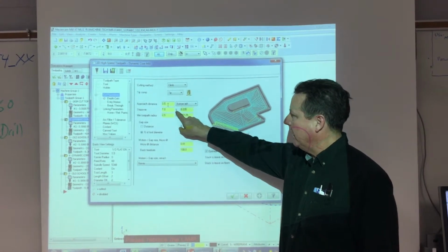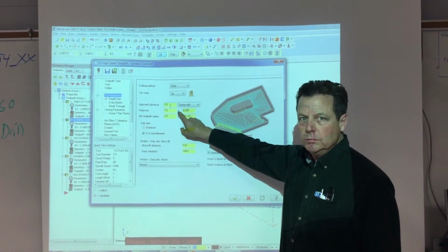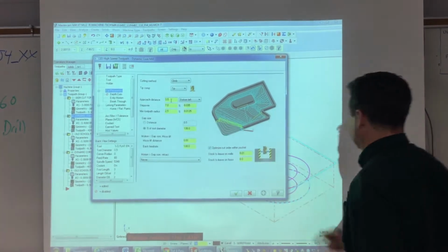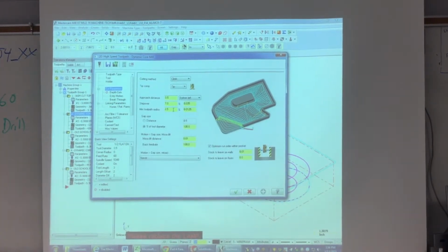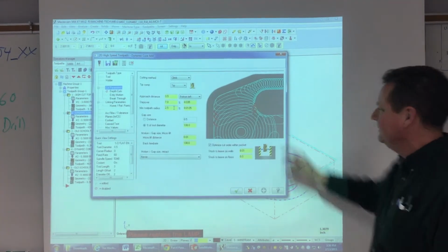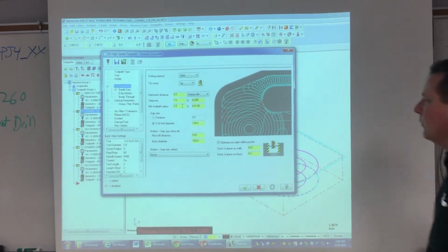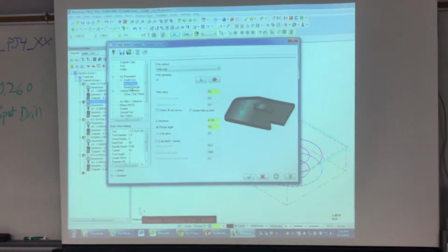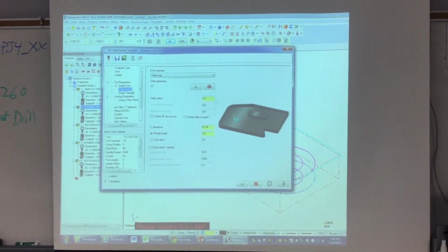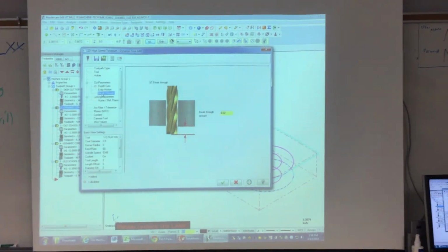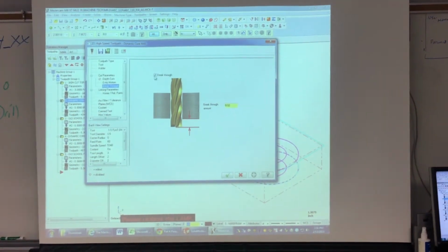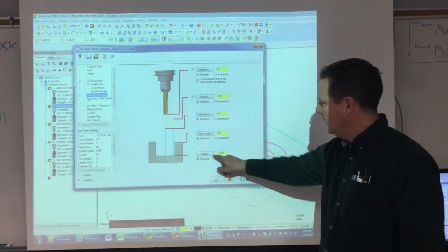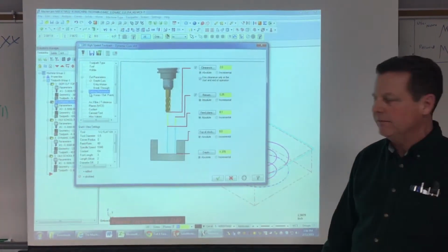7% of a 1/2 inch diameter tool is going to be 35 thousandths. The minimum tool path radius sets these little radiuses in here where it's cutting. I left 10 thousandths on the walls and nothing on the floors. Entry motion, I just made one quick little change to the radius there. I make it a little smaller than a 1/2 inch. I wanted breakthrough in this case. And then the depth with this end mill is 1.375.